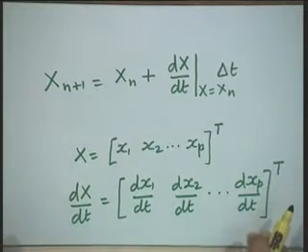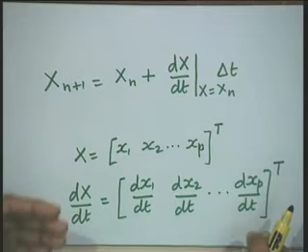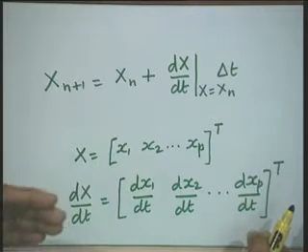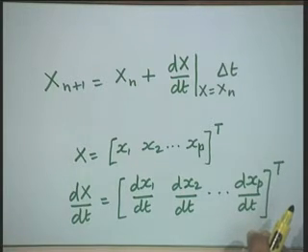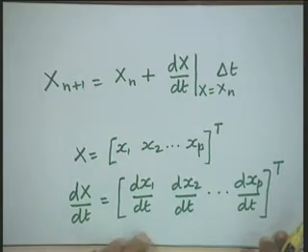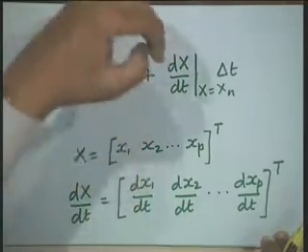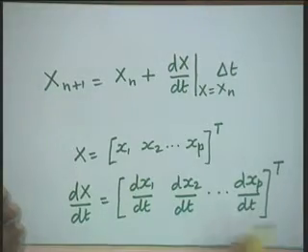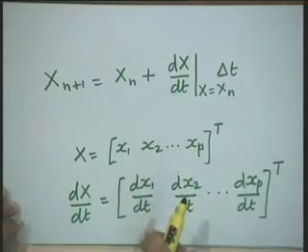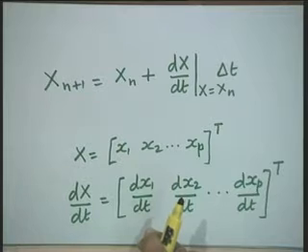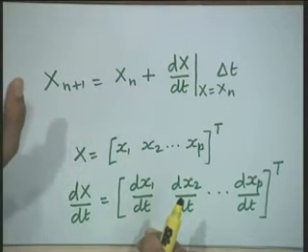This is the way this is to be obtained, because when you write down the set of first order differential equations, on the left hand side we have the derivative terms, delta 1 dot, delta 2 dot, delta omega 1 dot, delta omega 2 dot, like that, for our stability analysis. Therefore, these are all derivative terms. These are individually evaluated. Now, when I say that dx1 by dt is a function of all the state variables and initial conditions.